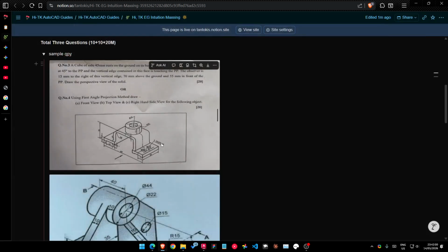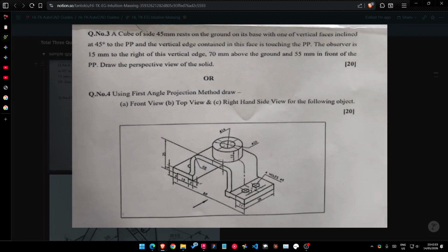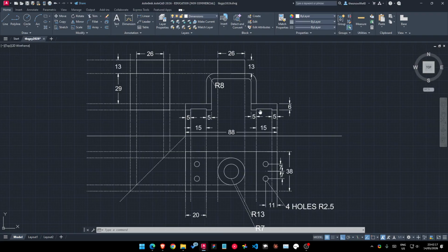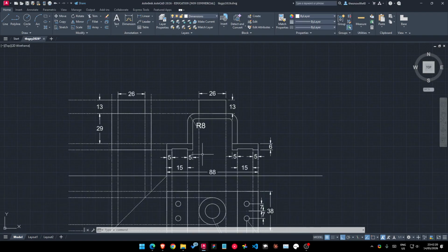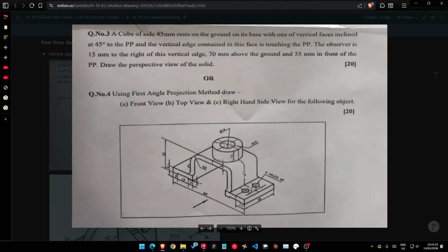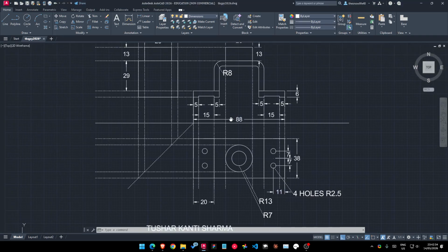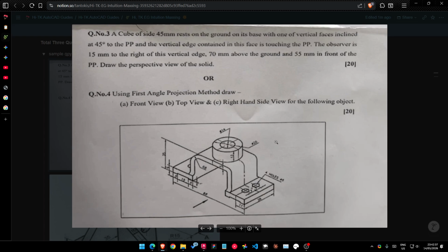So what I did was, I had a rough page with me, and I very quickly sketched a rough diagram of what the final drawing should look like. First of all, this front view, we will be drawing this. Let me show you. This is the front view, and this needs to be drawn above this plane. And the top view would be something that we see from here, and this is what this would look like. You feel me? If we're looking at it from the top, this is what we would see. So quickly sketch something out, and you'll be way quicker.